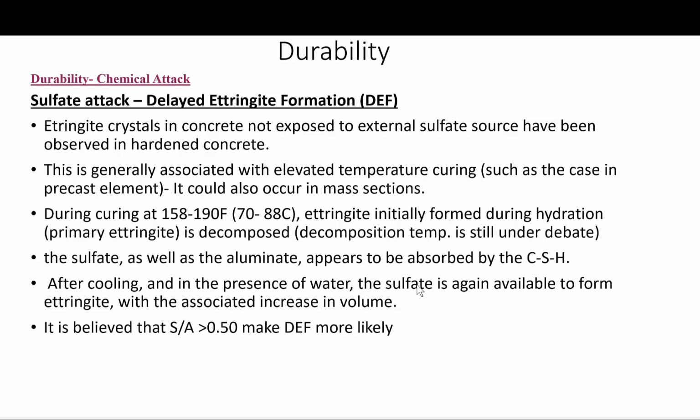Neither, however, provides rapid results, and many different approaches have been used. We have ASTM C452, which is proposed for research purposes only. It uses basically an abnormally high gypsum content in cement to test the sulfate resistance. It is a test for the cement only and not for concrete.